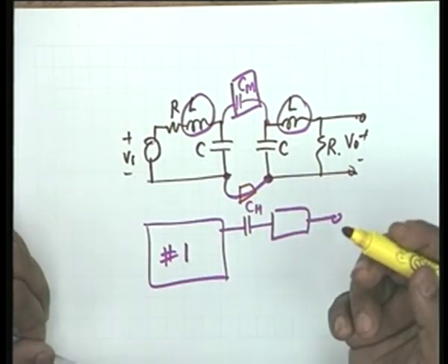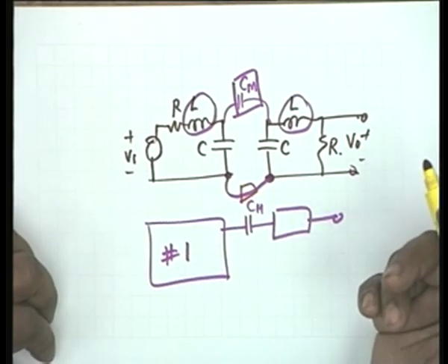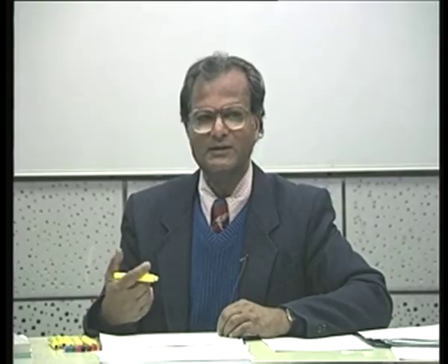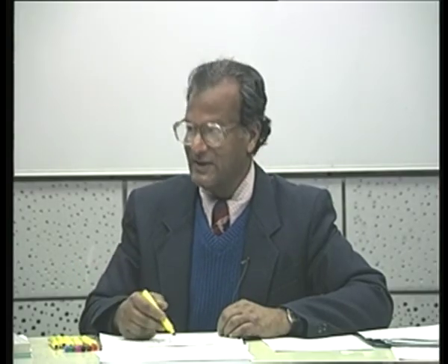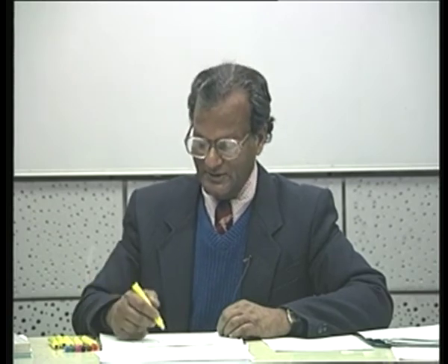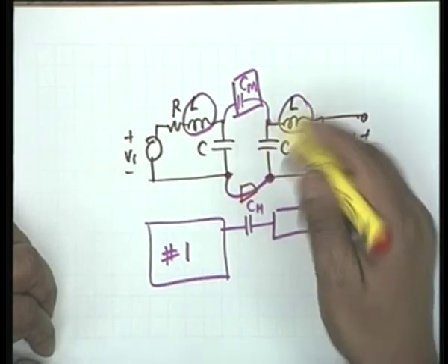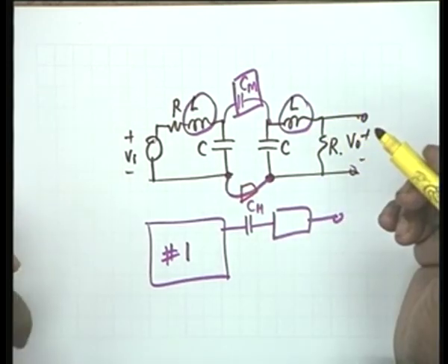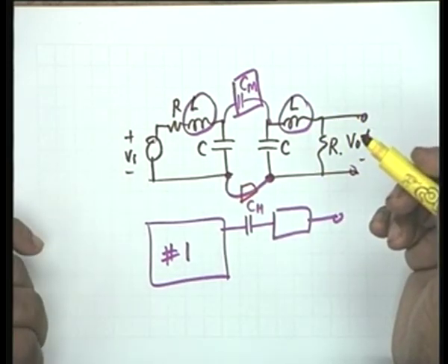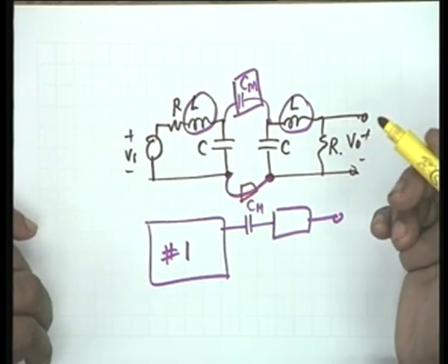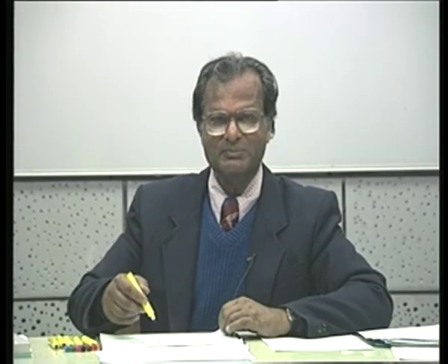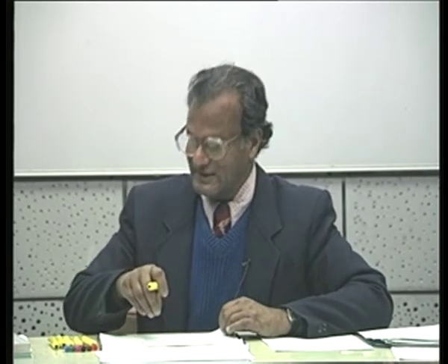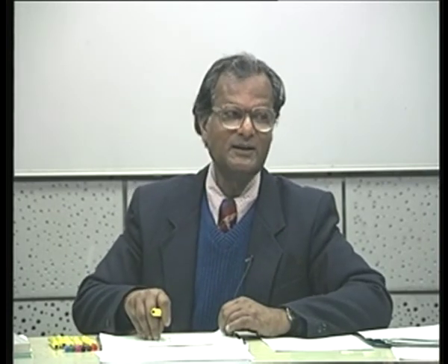Well, this may be connected straight or may also be connected to another impedance. It doesn't matter. The hybrid coil that you see in telephony is an example of such coupling. It could be any impedance that you like, provided the impedance is not infinity. If the impedance is infinity, no current can flow. This electrostatic coupling can be dealt with exactly the same manner as inductive coupling.